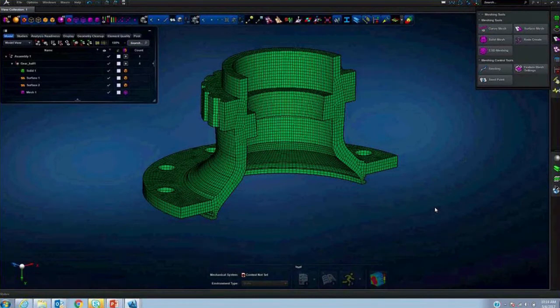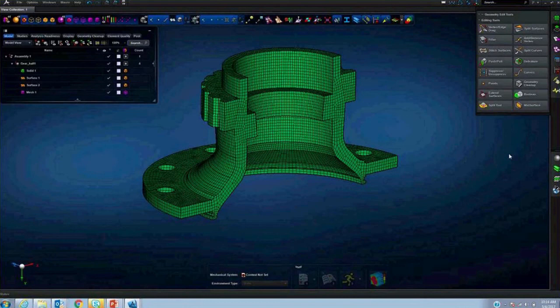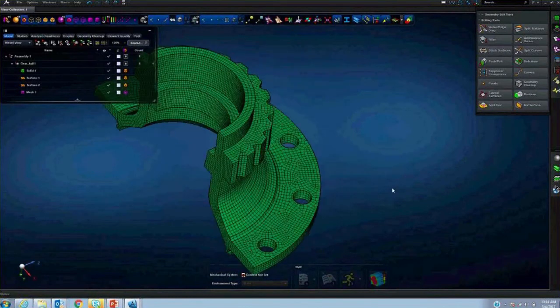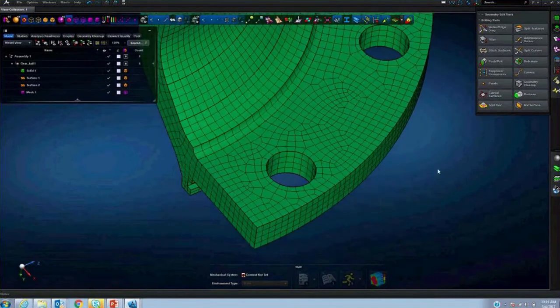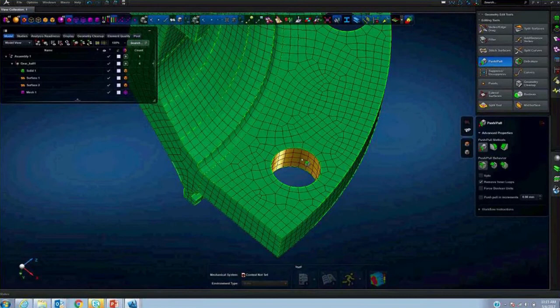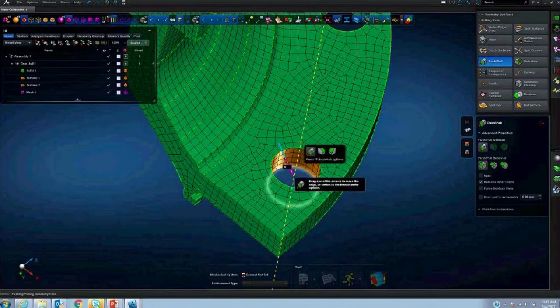But while we are here, now can we take the power of Apex to do some geometry operations so that we can see the generative behavior of the mesh updates? For example, if I go to the push-pull, can we reduce the diameter of this pole, for example, from 12.5 to 9, let's say?